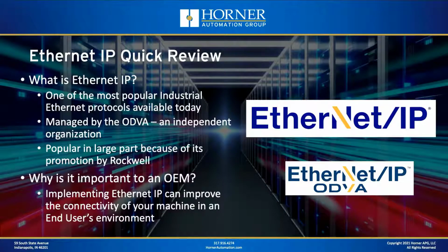Now for our quick review of Ethernet IP. So what is Ethernet IP? Well, certainly it's one of the most popular industrial Ethernet protocols available today. It's an open protocol that's managed by an organization called the ODVA. They were originally formed as the manager of the DeviceNet specification, but since that time they have added many other protocols, and Ethernet IP is definitely a prominent one. Now, the reason why Ethernet IP is so popular is largely because Rockwell Automation promotes Ethernet IP, and they have, of course, the number one market share in North America for automation.